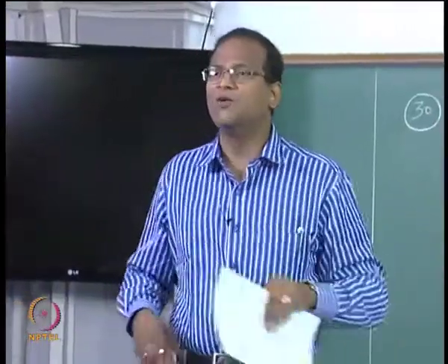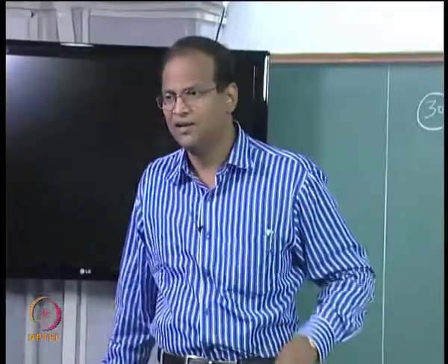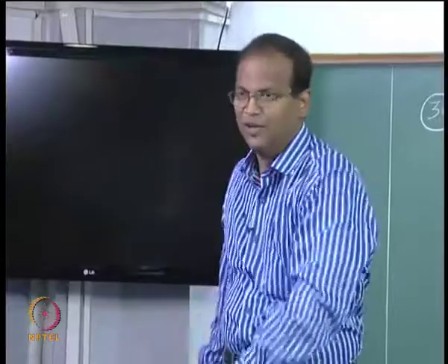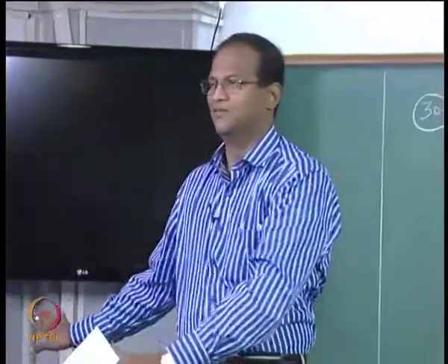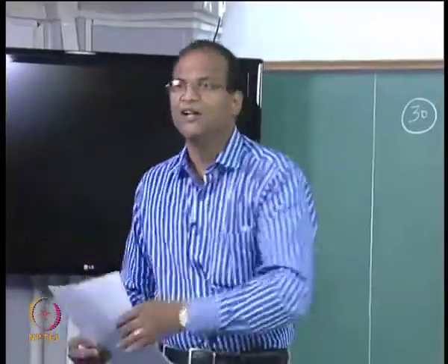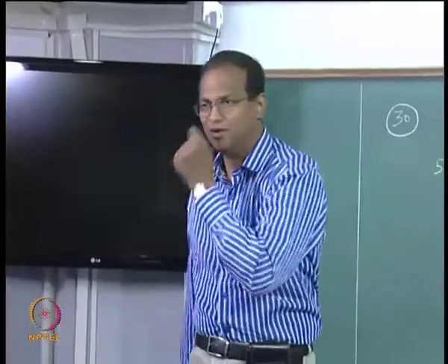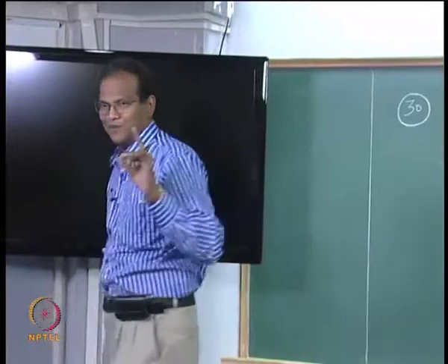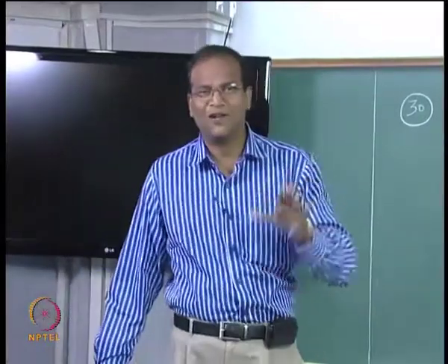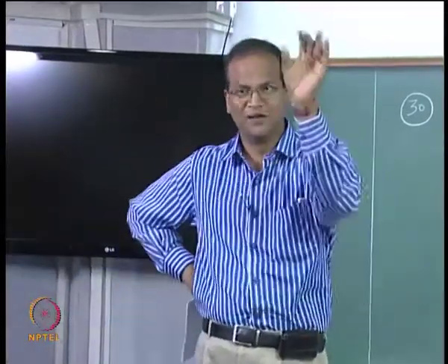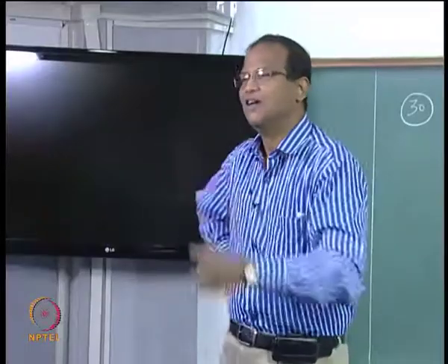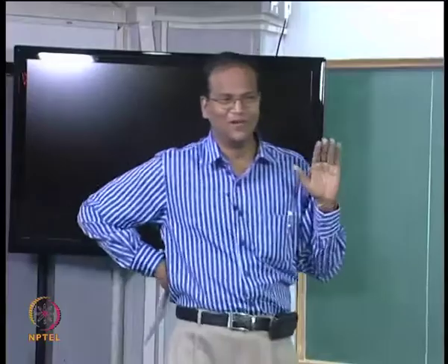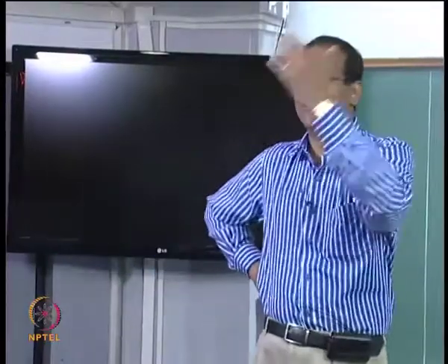The other risky route would be to disregard all that completely: F1234 is equal to F123 plus F14, and you keep on doing that till you get an expression for F12 in terms of all the other things, and then substitute A1, A2, A3, A4. This is high risk from a student perspective. It is better to just list out first the areas and list out all the view factors. At least the teacher knows that you know how to read the charts and how to get the basic view factors, then you can start off with your algebraic manipulation.